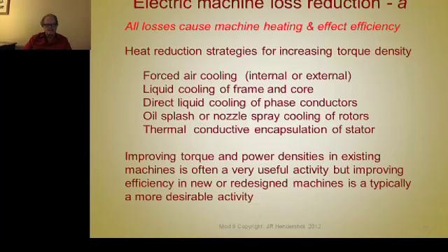induction machines. And of course, another thing that helps with the hot spots is to encapsulate the stator, or at least the end turns, in a good thermal conductive material, the types that I spoke about in an earlier lecture, that has high thermal conductivity. Some of these new thermoplastics and epoxies that are filled with the nitride materials and oxide materials that improve the thermal conductivity.